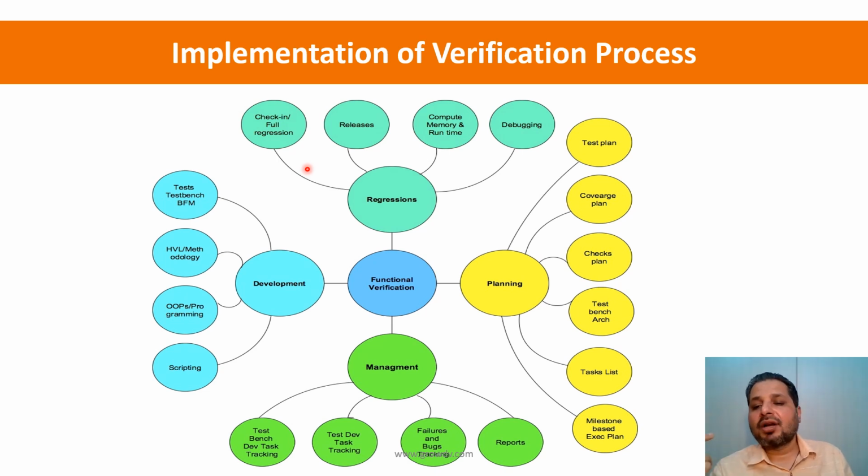Now one might ask, why not run all the 40 tests? It takes a lot of time. In a given day, if bigger teams are involved and there are a lot of changes, everybody running all the tests might end up consuming a lot of compute resources and licenses for the tools. So you run a subset of tests to make sure nothing is fundamentally broken, and you go ahead and commit the code. And then at the weekly level, you start running full regressions, which are made up of all your tests, so all 40 or 100, whatever. Whatever has been passing so far, you run all of them and make sure that there is nothing broken. And if something is broken and you find failing tests, you bucket them.